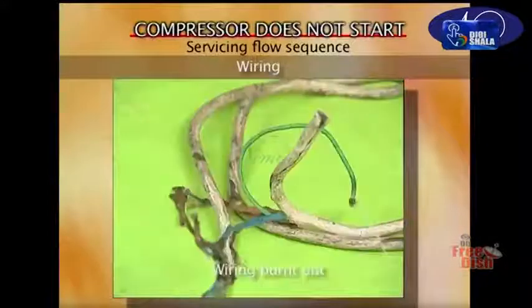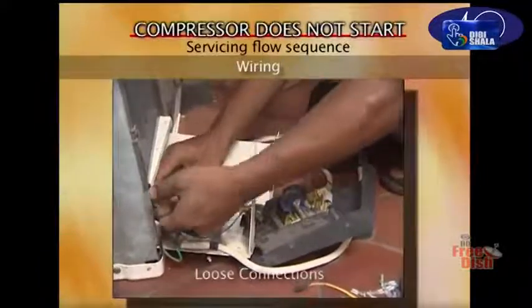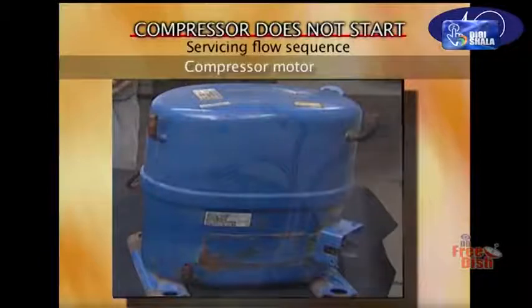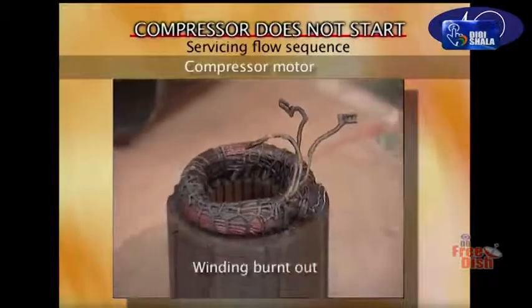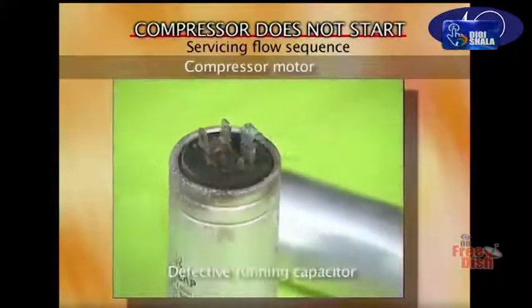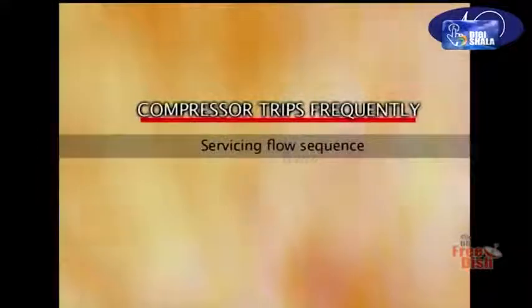Either the wiring is burnt out or there could be loose connections. Check the compressor motor. The windings could have burnt out. Defective running capacitor.